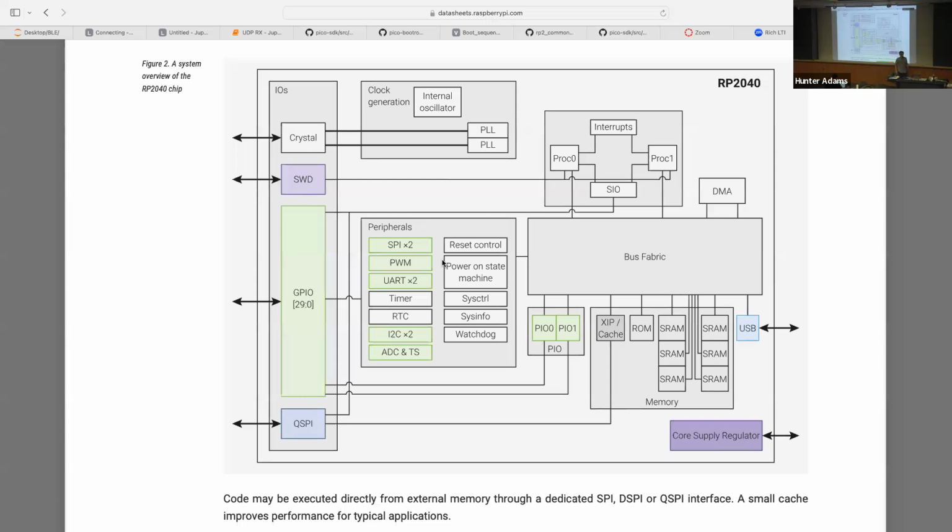Now, I'm going to abridge the story of the ROM a little bit, but in short, what the ROM is responsible for doing is figuring out whether or not there does actually exist a valid program in flash memory, and furthermore, figuring out which of the handful of compatible flash chips with which I might be communicating am I actually communicating.